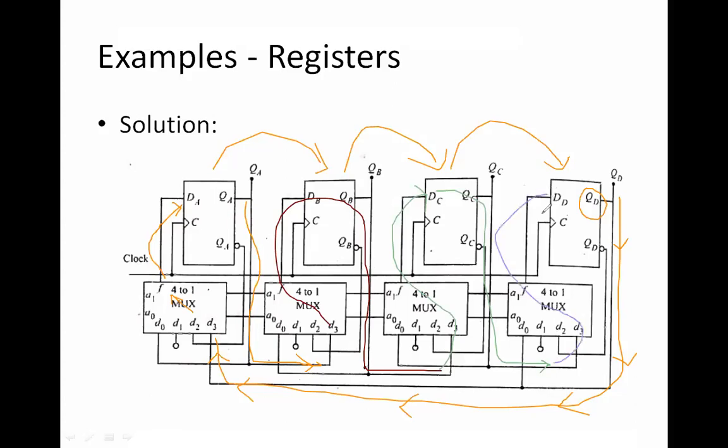So ultimately, you can see that the final bit is traveling across, and we are giving it as feedback to the first multiplexer. With this path, it is able to travel through all these flip-flops and then come across and sit in the final one.